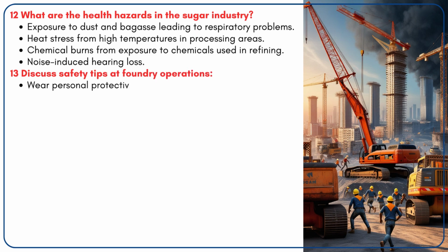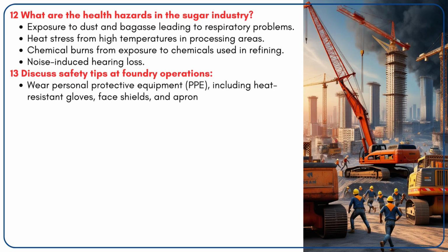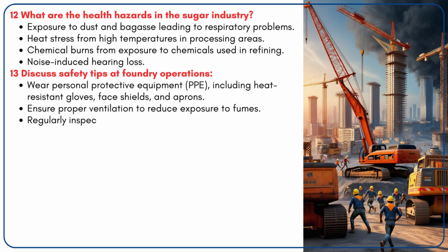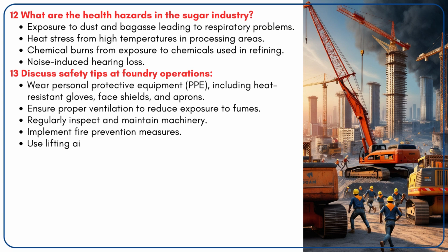13. Discuss safety tips at foundry operations. Wear personal protective equipment, PPE, including heat-resistant gloves, face shields, and aprons. Ensure proper ventilation to reduce exposure to fumes. Regularly inspect and maintain machinery. Implement fire prevention measures. Use lifting aids to prevent manual handling injuries.